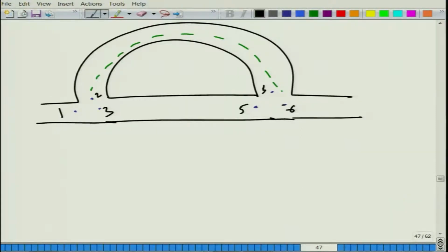But what I am trying to say now is that this element is a 2 port element, because there are only two ports. It is best not to talk in terms of inlet and outlet, just 2 ports, where either you can relate the pressure and mass velocity here to the pressure and mass velocity there, or else you can relate the acoustic pressures here and here with the respective mass velocities through an impedance matrix.